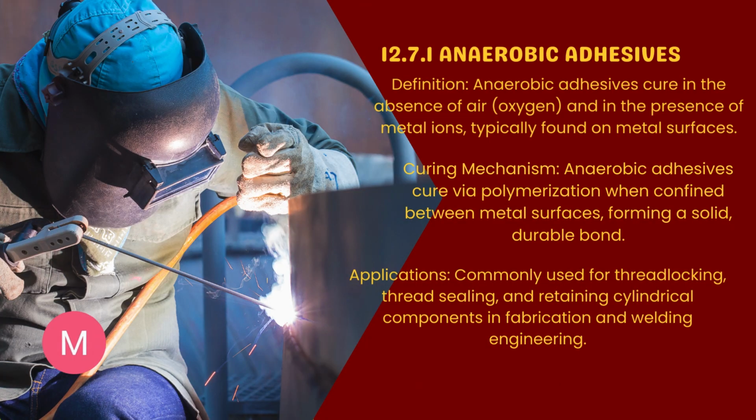For subtopic 12.7.1, anaerobic adhesive. The definition: anaerobic adhesives cure in the absence of air, oxygen, and in the presence of metal ions, typically found on metal surfaces. The curing mechanism: anaerobic adhesives cure via polymerization when confined between metal surfaces, forming a solid and durable bond. Application: commonly used for thread locking, thread sealing, and retaining cylindrical components in fabrication and welding engineering.